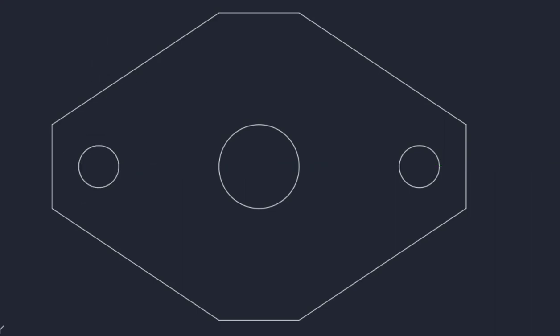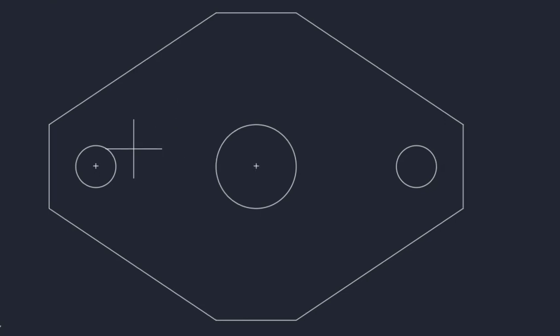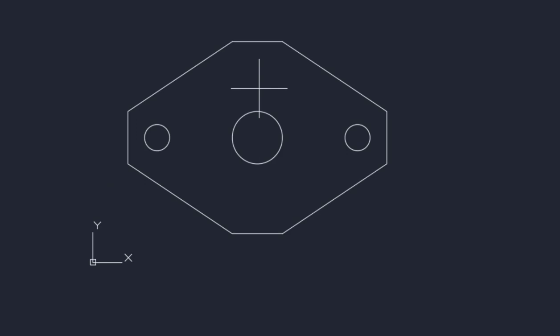A couple of things to watch out for when doing this. It is possible to track multiple points, so you might do this by accident. So here I've acquired several different points, so my screen can get kind of messy. If you acquire points you don't want, you can unacquire them just by hovering your mouse over them again, and they will go away. It's important to note that zooming your screen will also eliminate an acquired point. So here I've acquired this point and I'm tracking, but I rolled my mouse wheel and I lost it.